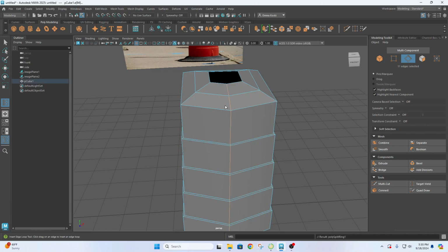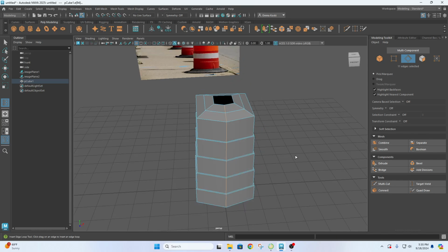For some of you, if you click it and the green dashed line is behind your object and doesn't go all the way through, that means you're grabbing those back faces. That's not good. So hit Control Z, and let's grab this front part of our object. Try and get about in the middle, and then let go.